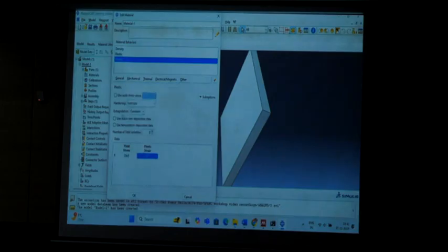And here we have the options like use strain rate dependent data, use temperature dependent data. If you click on this, it will ask you the temperature, like whether it is at room temperature, what will be the values at other temperatures, depends on what temperature you're working on. Someone will go for 100, 200, room temperature and everything. If you don't want to be more complicated, then just unchoose this option.